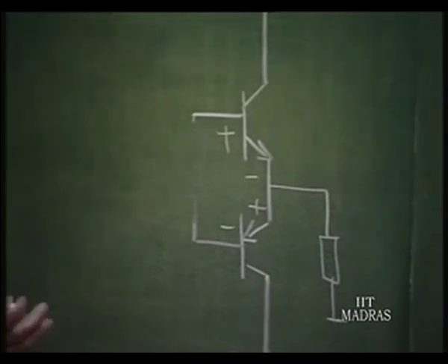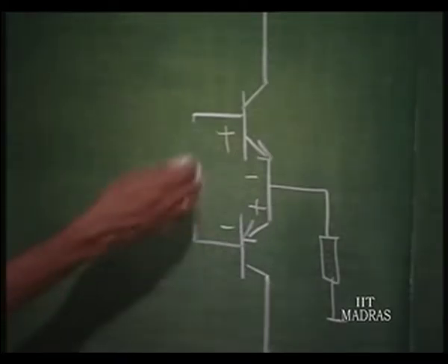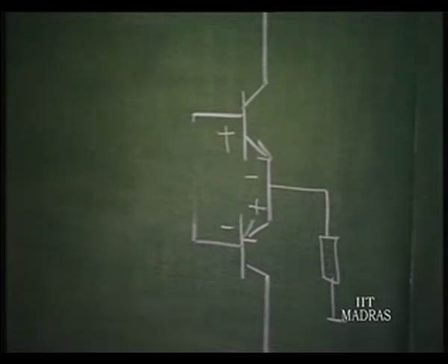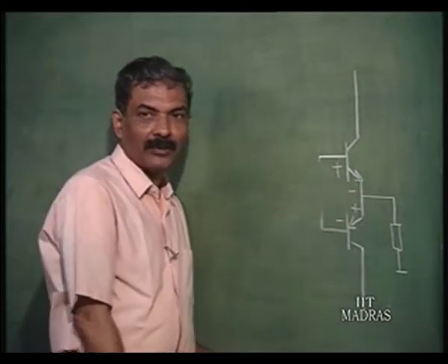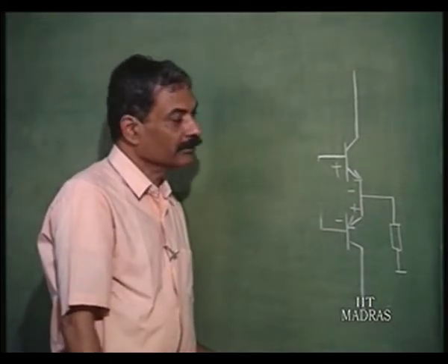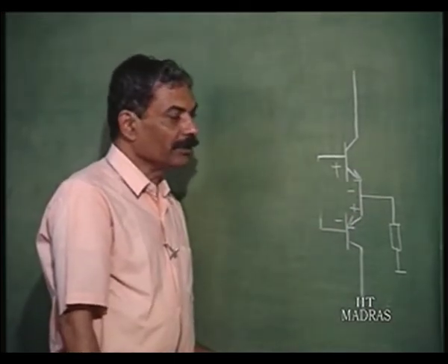The transistors will not conduct throughout. So, output will be 0. So, the extreme limiting factor is when the peak amplitude of the sine wave is of the order of 0.7 or less, nothing comes at the output. So, what to do about this?